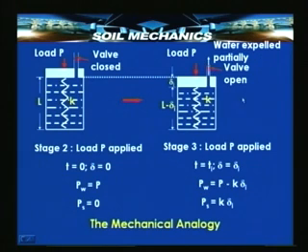The valve is open, water flow is still taking place, and at any time t_i, an intermediate instant, the compression that has taken place is delta_i, and the load that has been taken up by water is therefore the total load P which it was originally carrying minus the load now which has been transferred to the spring, because the spring has undergone a compression equal to delta_i.